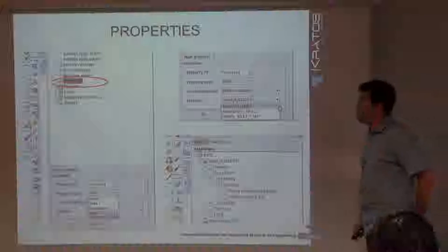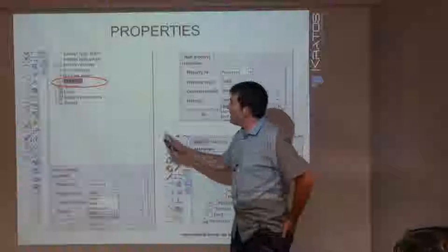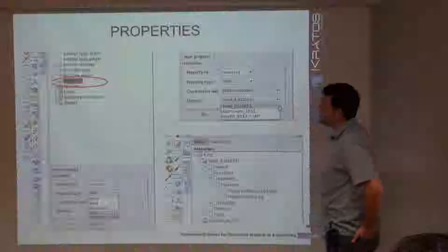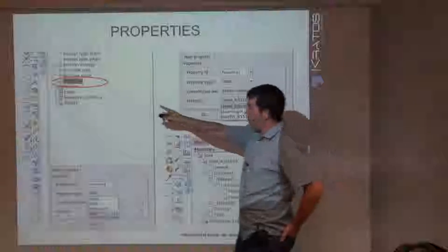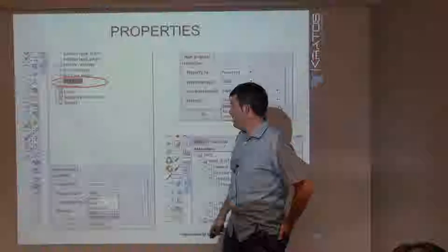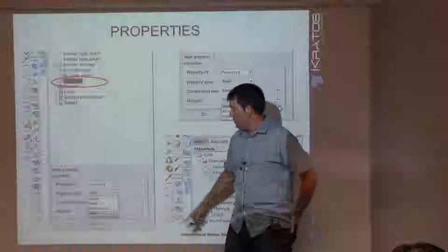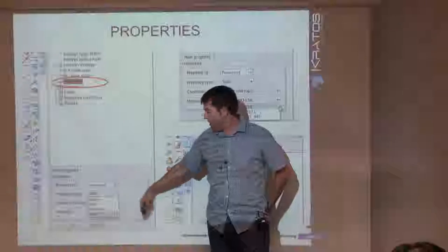And once we have the geometry, we start with selecting the data that we are going to use. So the first thing is selecting the properties of the material. In this case, we go to the properties, we click here, and this menu is open. The first thing is the property ID. We can change the name if you want.